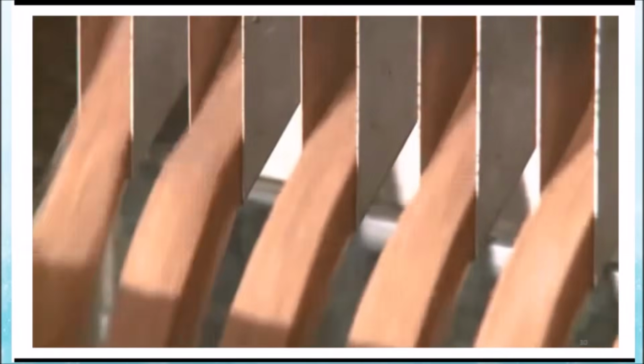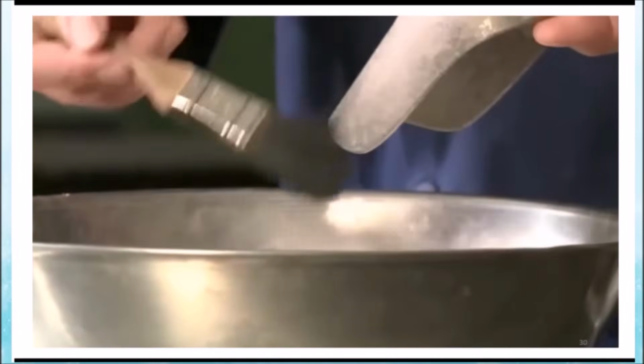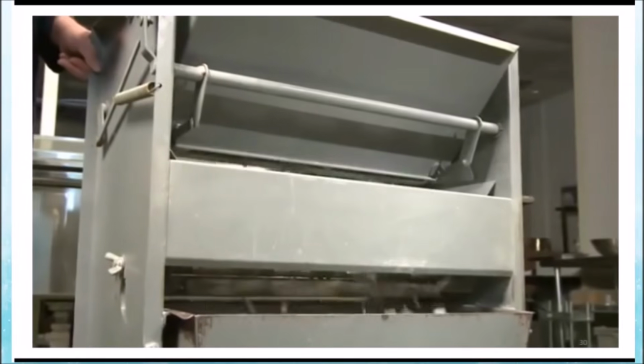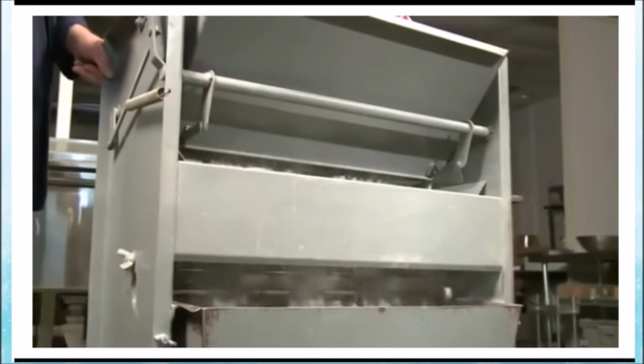Remember, the purpose of this standard is to reduce a field sample to testing size while maintaining the representative nature of the sample. Method A is preferred when applicable. It is important to collect all fines and to avoid any loss or contamination of material.